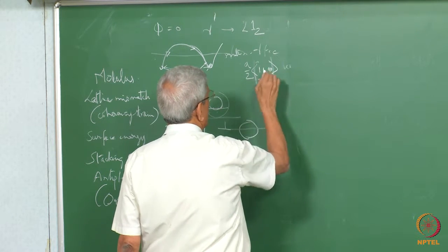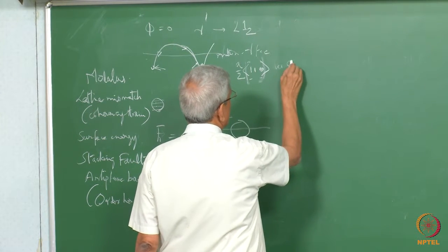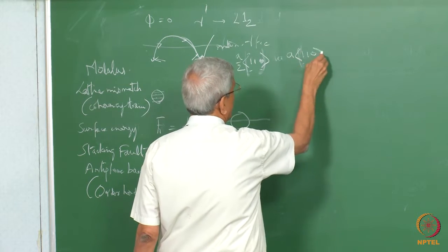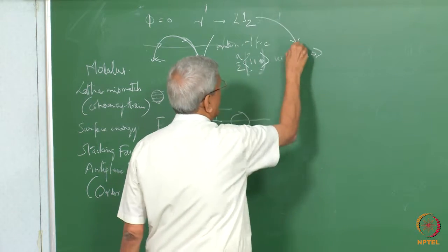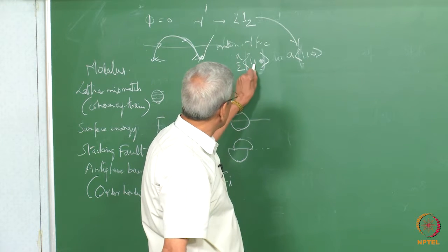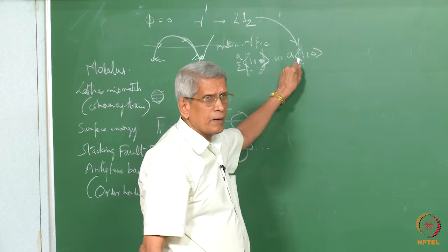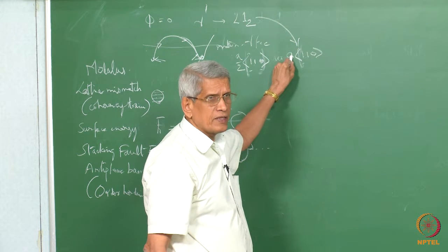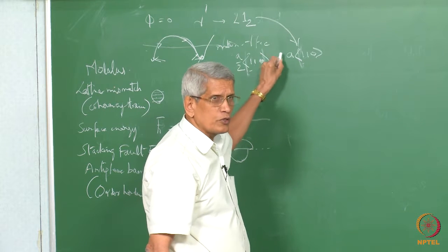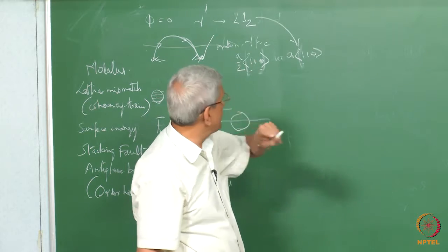The Burgers vector of a perfect dislocation in L12 is a<110>. Since the magnitude of the Burgers vector is large, the self energy is high, so it would try to split into superpartials. All these aspects we have considered earlier.